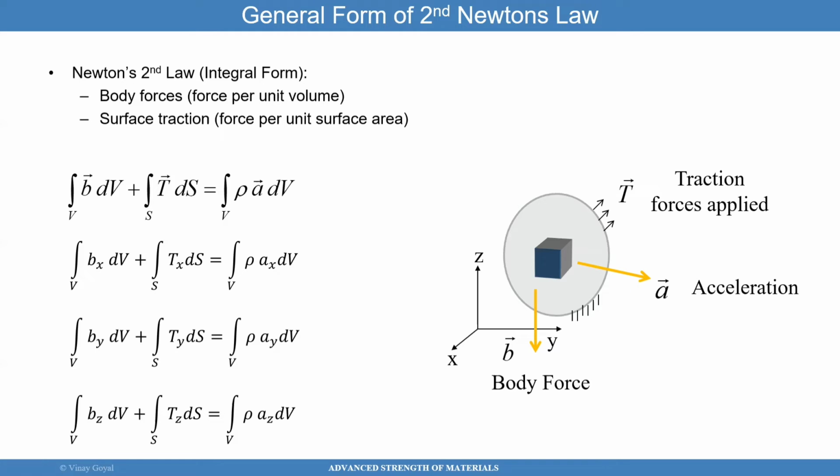So let me apply a more general form of Newton's law. If you recall, integral means summation. So what I'm going to do is take a little cube of material. I know there's a body force acting on this volume, but it is also acting on this little cube. So I'll apply the body force to that little cube, dV, a small differential volume, infinitesimally small. So body force times dV is the force exerted in a particular direction.